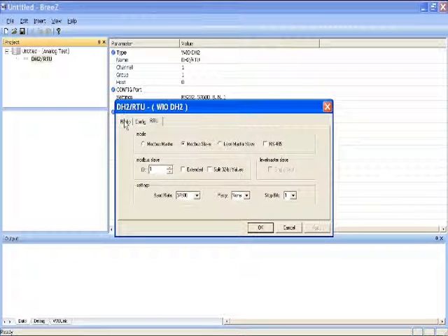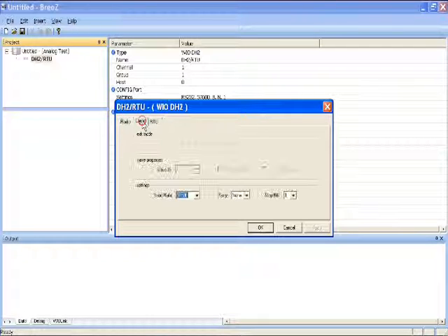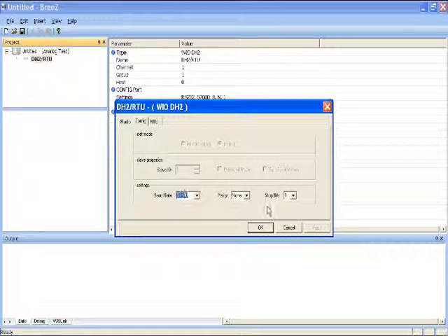Set all parameters for the DH2, starting with radio. Since there is a power supply available, you have the availability of setting up to 1 watt of transmit power. 1 or 10 milliwatts should be sufficient, especially for testing purposes. Leave retries at 16. Go to Configuration tab. Configuration should remain at 57600, none and 1, for this is the port in the back of the DH2 that you come in with Breeze.